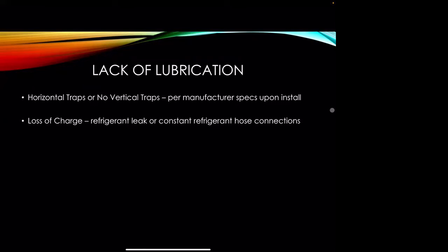Little tip here on the side that I didn't put in here as well. It's not really ever the Schrader. It's not the valve core. We see far too often in our field and in the HVAC industry that people will charge it back up and say that they fixed the leaking valve core. How often is it a valve core on your tire? Yeah, it's usually not, right? It's usually leaking somewhere else. Again, it is not the valve core. Find the leak, let's fix the leak and stop this from happening, or we'll be replacing compressors.